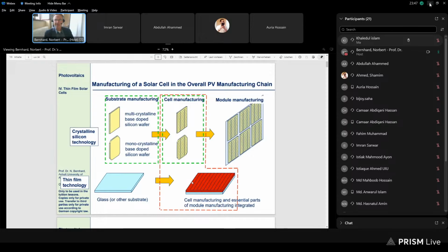The only thing which is preserved, or almost preserved, is the next neighbors of a single atom, but there is no long-range order. On the other side, you see there are small crystallites, really microcrystallites. That means there are small regions where it's arranged, and therefore this is called microcrystalline material. If it would be completely random, then it would be amorphous material.